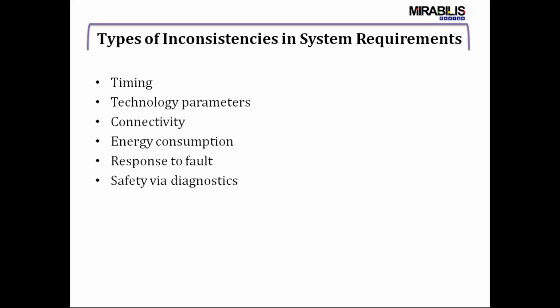For example, let us say you are working on a low power device requirement and you're using a DRAM running at about 200 megahertz, and you're expecting a particular data rate or throughput from that memory, but you're not going to get that. You will end up with processor stalls, or the success of that particular application completely vanishes.